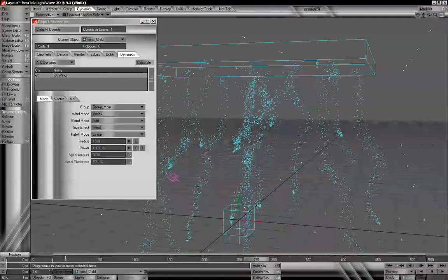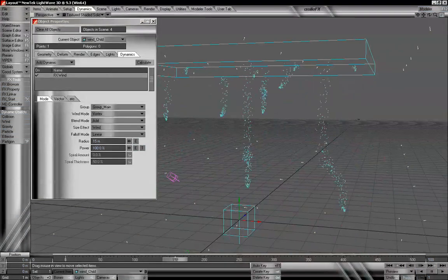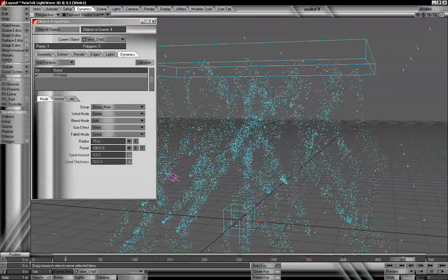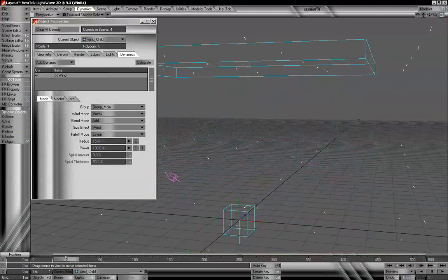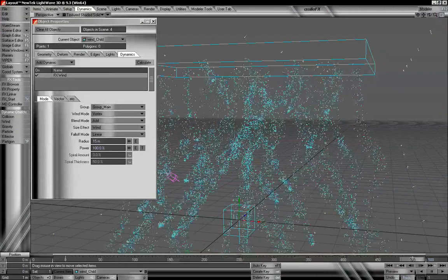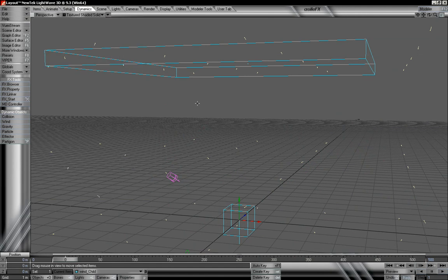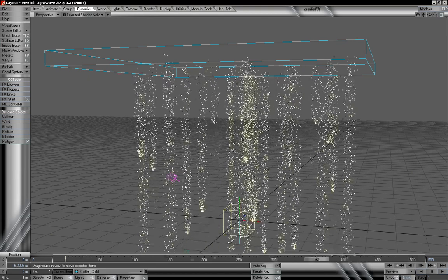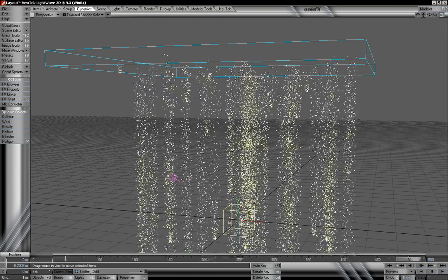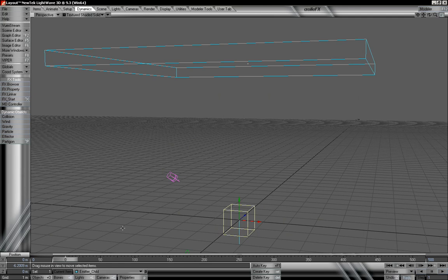Now we can also use collision objects and the way each of these particles end to create some more variation. So let's take a look at that now, and what I want to do is first remove this wind object from our scene. So now we just have those straight falling particles. But let's take a look at another way of emitting our child emitter.